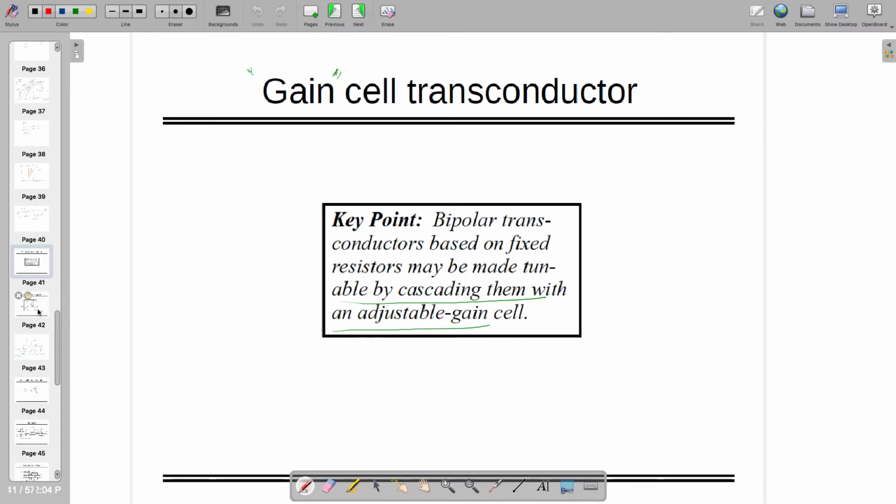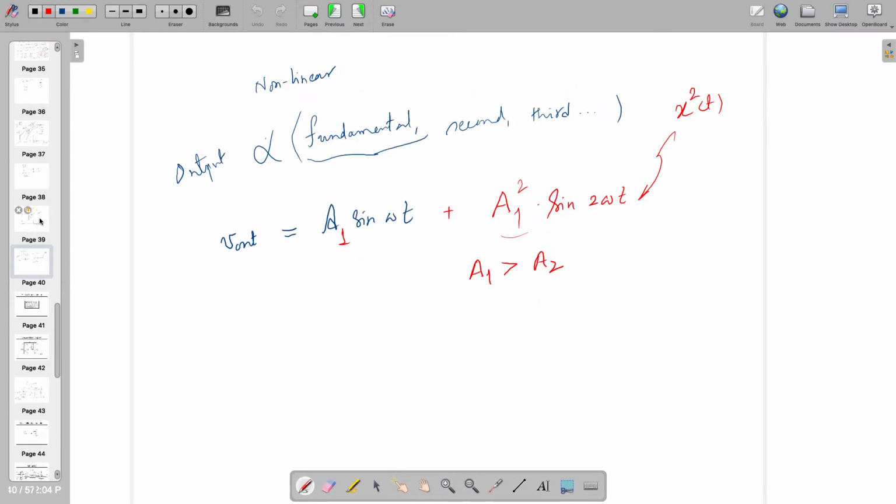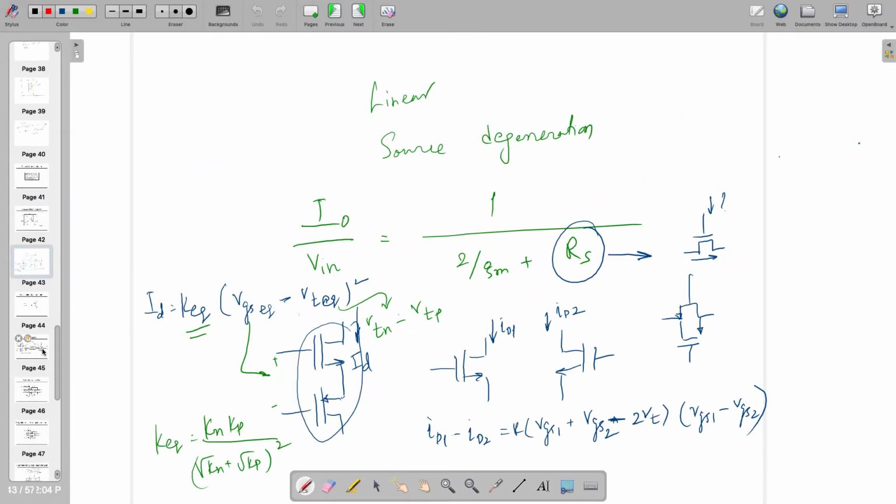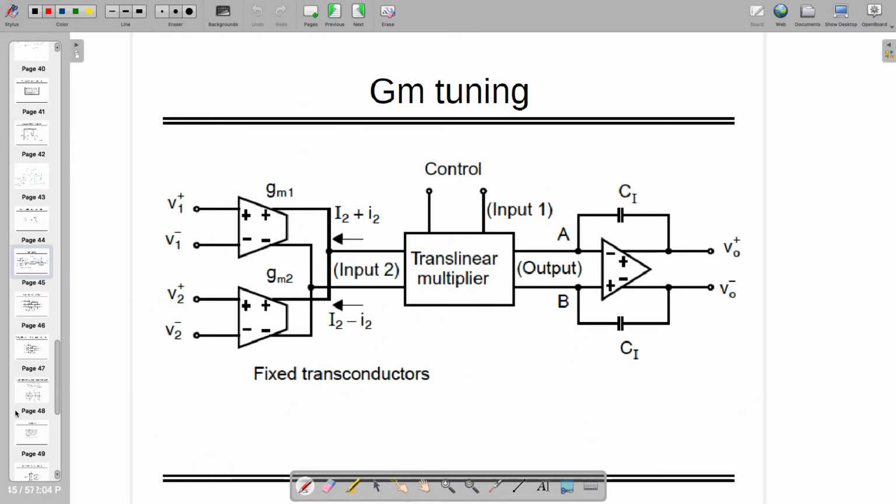So sometimes we are going to use these as your specifications, right? Anyway, I thought a lot and then I thought there is no need to discuss this circuit. But one thing is there, when you are designing a circuit which is a GmC filter, it's difficult to get the value which you want across corners. Like your Gm is actually open loop. At some corner you are getting very good Gm, some corners you are getting very poor gain, right?